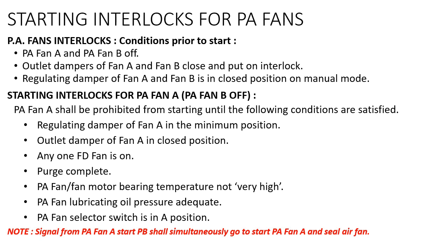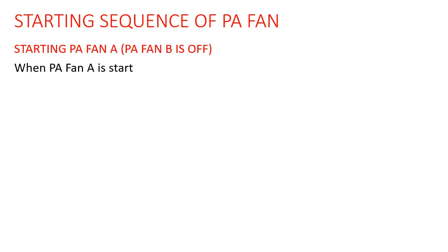When both the PA fans are off and we want to start PA fan A, as soon as you press the push button to start PA fan A, the seal air fan of PA fan A will start. The starting sequence of PA fan.